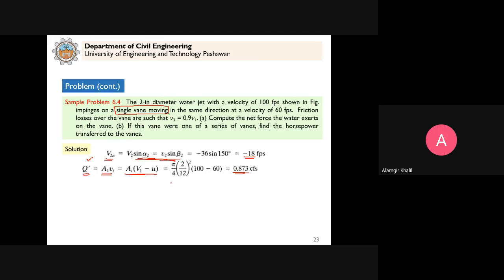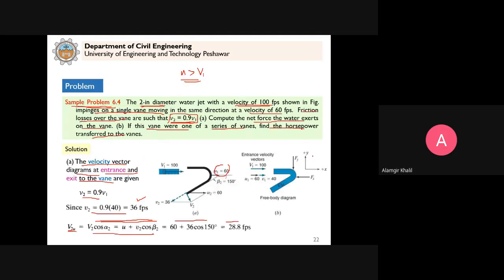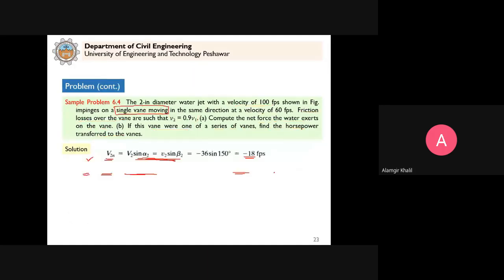Now we consider the forces here, plus x and plus y. These are the assumed directions of the forces in the x and y direction. In the end, the plus or minus sign will tell us whether these directions are correct or not. Clear? So this is minus fx, opposite to plus x, and this will be minus, opposite to plus y. So remember, minus x and then minus y. No other external forces are acting, so we consider only fx, fy, and the rate of change of momentum.